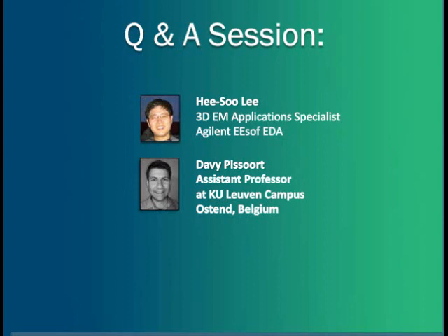Yeah, as I explained during my talk, the nature of the problem is more like 3D problems, especially chassis examples, and these are all 3D type of problems. That's where we need 3D EM solvers, full wave EM solvers. Technically, FEM and FDTD are 3D full wave EM solvers. However, based on the different type of problems, either one of those technologies can be used, but